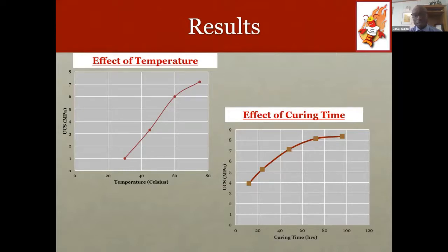We also checked the effect of curing time on this geopolymer mixture. What we did in this regard is we increased the duration of our curing, and we looked at the strengths that resulted. So when we looked at different times, starting from 12 hours, 24 hours, 48 hours, and 96 hours, we found that the strength also increased as the curing time increased.